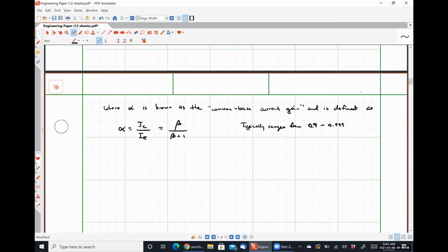So from these different definitions, our operational equations are: our collector current is IS times EXP VBE over VT. We're not going to go into great depth here, but this equation explains the amplification behavior pretty succinctly, right? For a very small change in VBE, we should see an appreciable change in the current because there's an exponential relationship between the voltage and current. So we can significantly amplify small voltage signals and turn them into macro scale current signals by using a transistor.